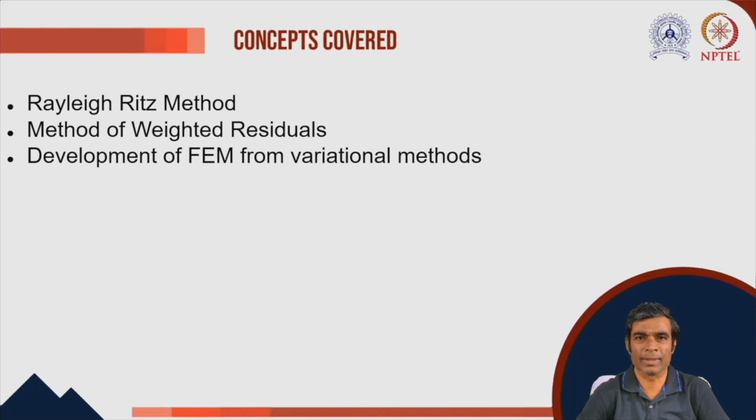In today's lecture, we shall elaborate upon the variational methods. We shall start with the Rayleigh-Ritz method. Then we shall discuss the method of weighted residuals. We shall show examples from 4 fundamental method of weighted residual techniques, and eventually we shall close today's discussion by discussing the implementation of variational methods in formulating the finite element techniques.